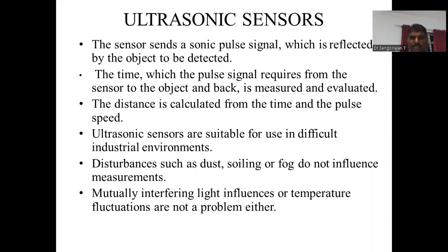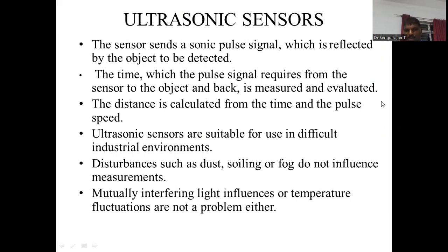Ultrasonic sensor is nothing but a sensor which sends a sonic pulse signal, which is reflected by the object to be detected. The time which the pulse signal requires from the sensor to the object and back is measured and evaluated.